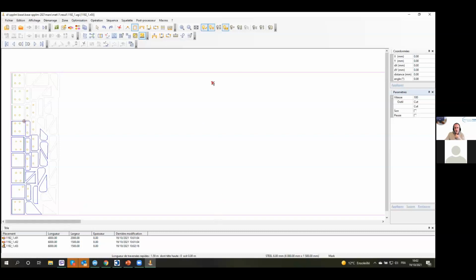You need to know that you can divide a plate like that. You can divide it in 2 or 3 zones if you need. If you divide it in 2 zones, you could have one zone that will be filled, then a second one, and once the machine produces the second zone, you can download the first zone. So you can divide the plate in different zones if necessary. He's nearly finishing the simulation here, and it will make the offcut here. Great.